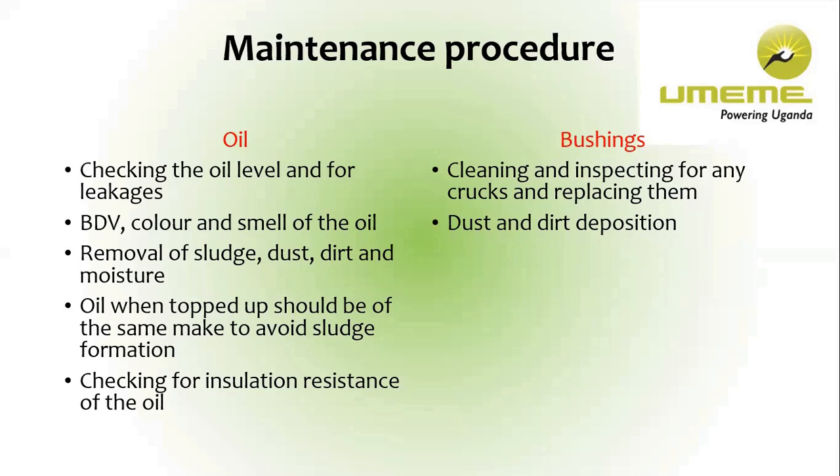We have primary windings and secondary windings, which are not supposed to be in contact at all. The moment they get in contact, that is an internal shorting, and it is a very big problem. Transformer oil is for insulating those windings from each other. Actually, the windings are also insulated by cellulose, paper made of cellulose.